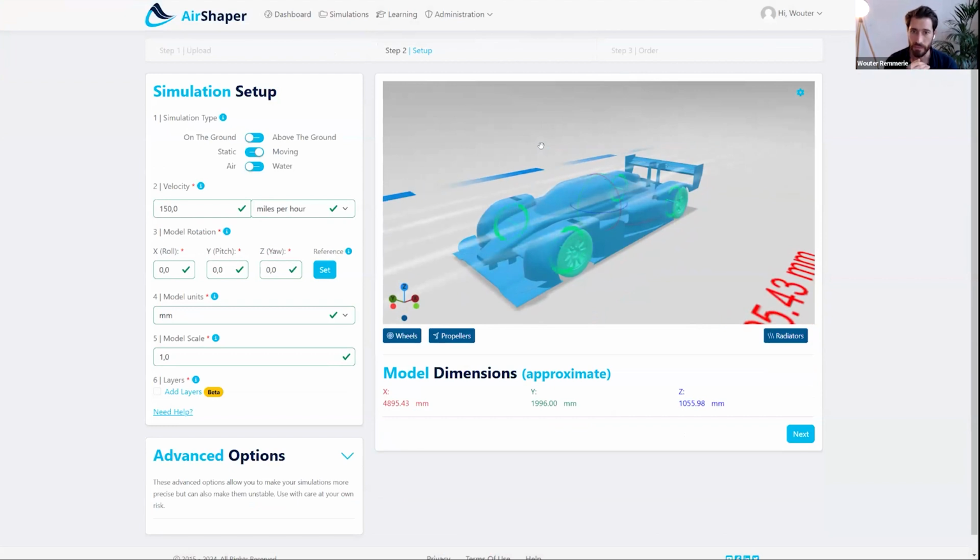And by watertight, I mean that every 3D model can have gaps or holes in between door panels or overlaps of surfaces, or can be full of components. Like maybe there's a gearbox assembly with 10,000 components in there or something. So we spent a lot of time to be compatible with what we call non-watertight models. So usually CFD software will crash if you haven't perfectly closed everything.